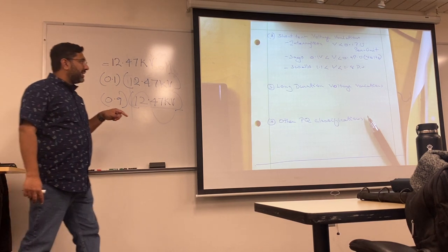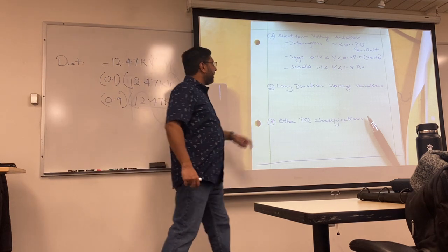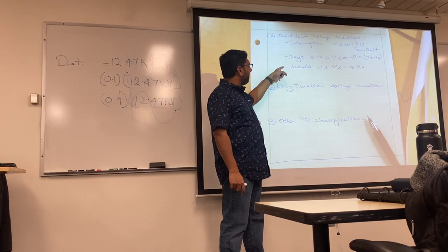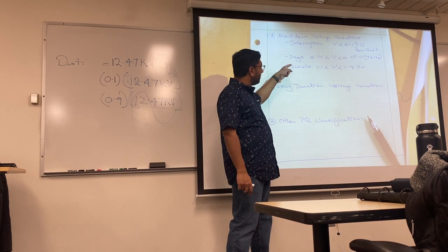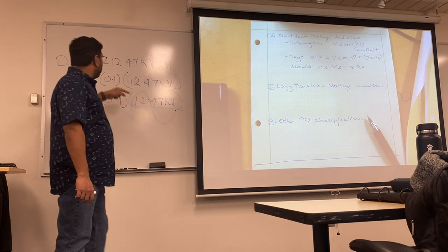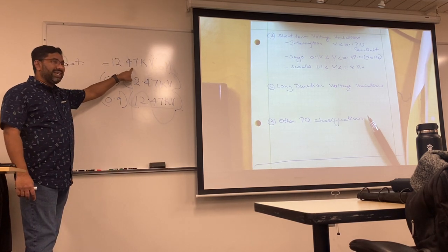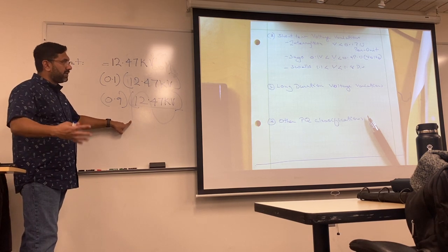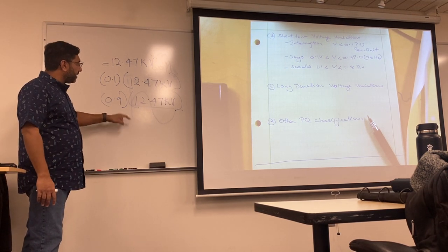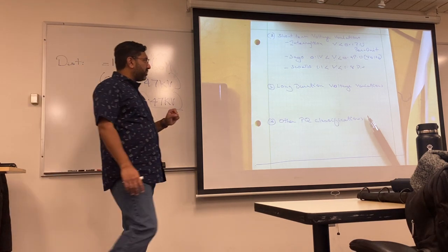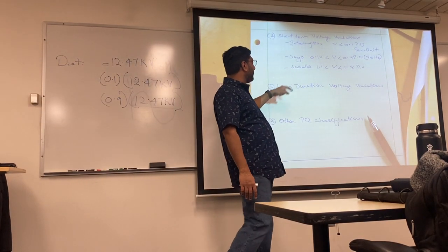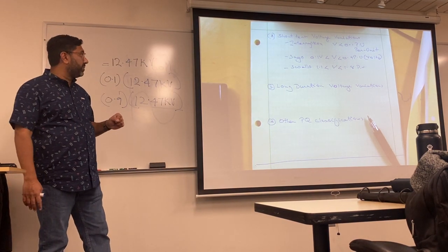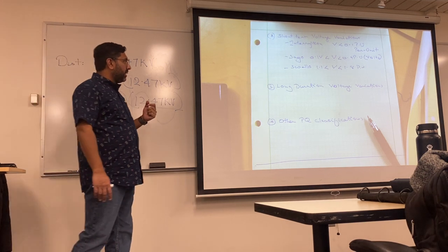sag. The sag typically happens when a lot of load comes into the distribution all of a sudden. So imagine everyone was driving a Tesla and all of them plug in their Teslas at the same time. Suppose this is 12.47. It is going to fall. Like the voltage will drop, like I just don't have enough power to push through. The swell, on the other hand, is kind of crazy. That happens when too many generators come up and start pushing power through a distribution line.